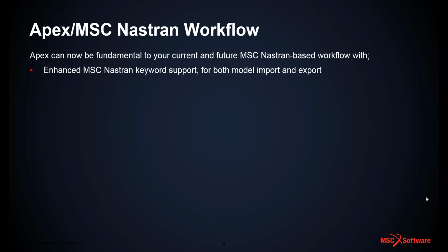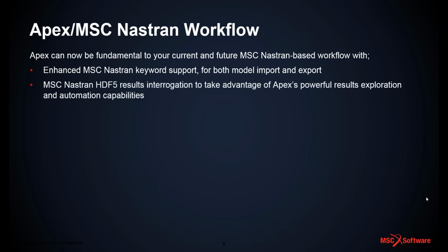Apex. So we have enhanced keyword support, both for reading models in and for exporting models. We have the ability to interrogate the Nastran format, the HDF5 result binary file, to take advantage of the powerful result exploration and also the Python automation within the Apex environment.